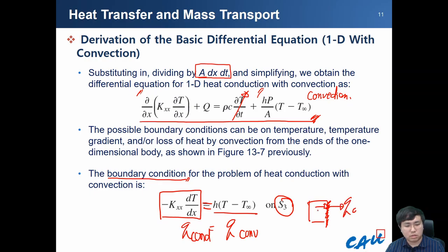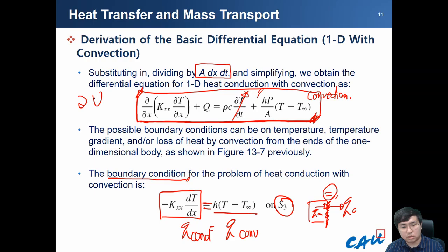This is a conduction. That must be equal to each other. We are going to say that this is a temperature boundary condition. So although we say that this equation is defined on a specific domain, mathematically on the specific volume domain, however, this convection is only defined on the specific surfaces.